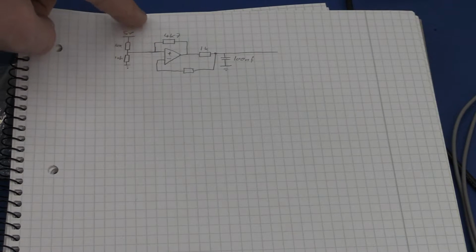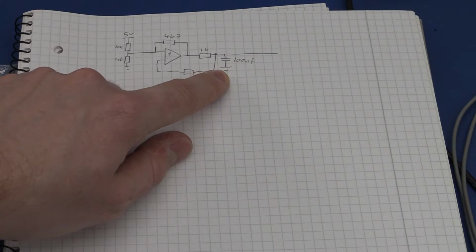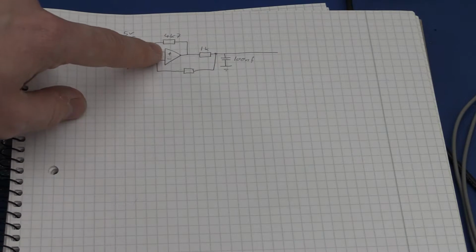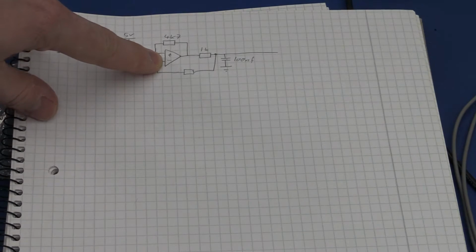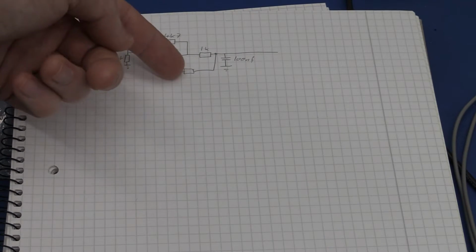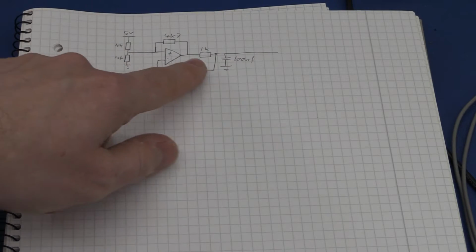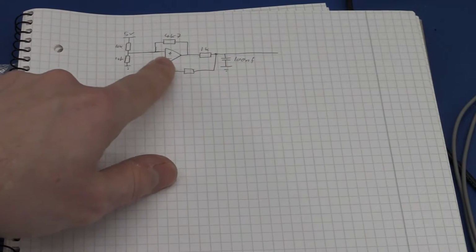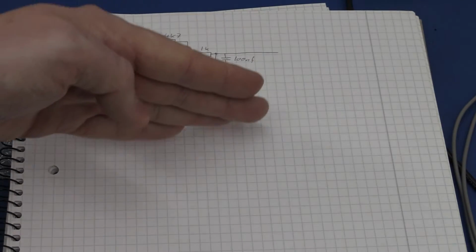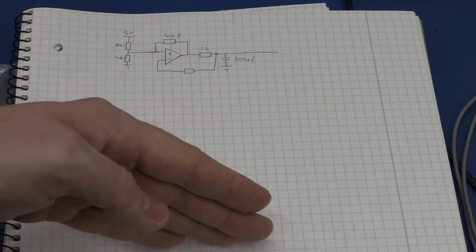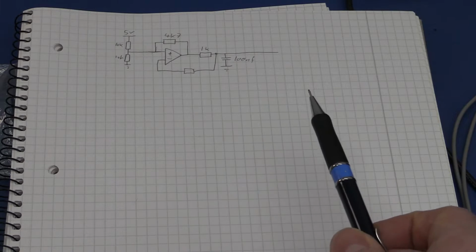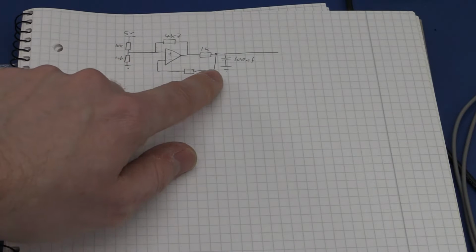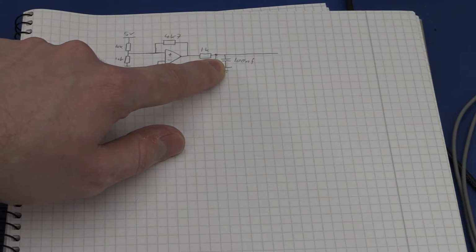Let's say it goes high, then the output will charge this capacitor, and when we hit this set point here on the output, it feeds back to the inverting, and the polarity will flip on the output, so it goes low. It takes some time to discharge the capacitor to the new reference, and once we hit the low point, it flips the output again and wants to charge up, charge down, up, down, so we make a triangular wave. But it is not truly triangular because we are feeding the capacitor with a fixed voltage.